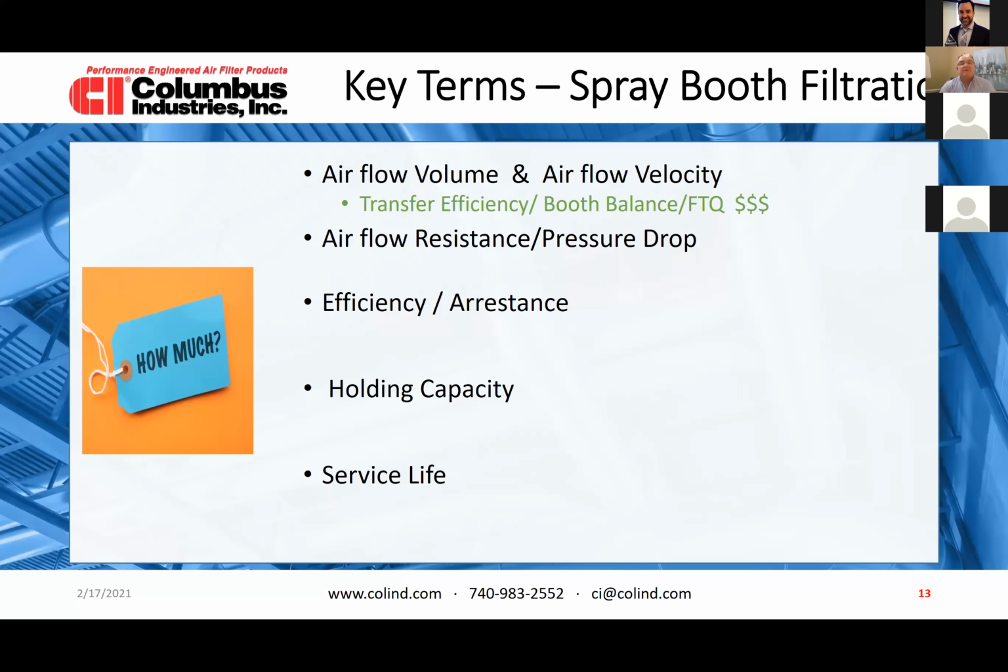When you have your airflow, if it's too high in one area because the other areas are plugged and you don't have balance in your booth, sometimes it does affect your transfer efficiency. In other words, you're spraying paint, and that paint is supposed to have a certain period of time to get onto the part, and then boom, it goes through, and some of it is lost to the overspray when it's supposed to be on the part.